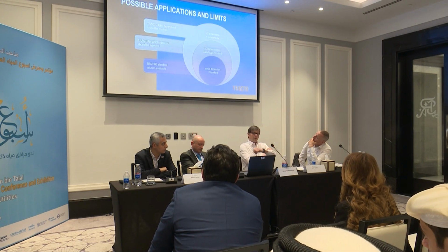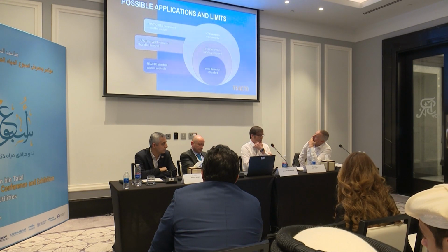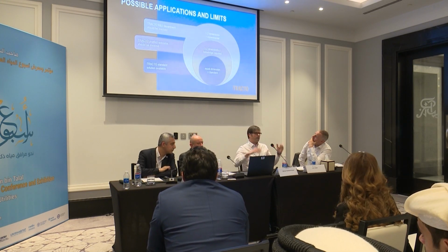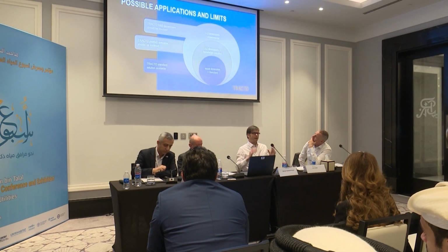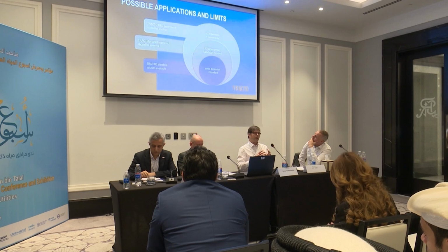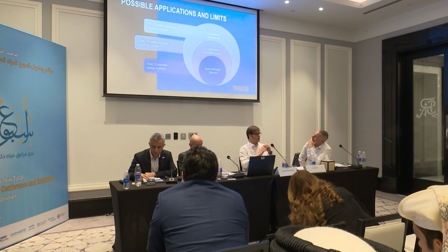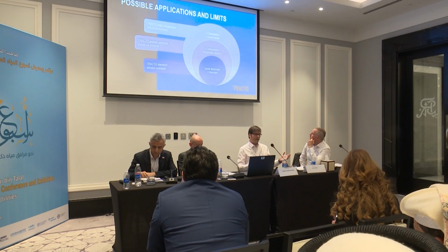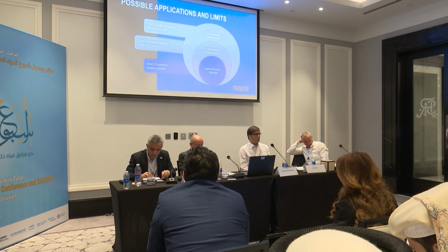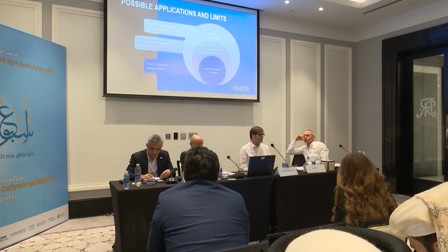So yes, one of our key USPs, unique propositions, is that we can upsize. We can install a larger pipe in an existing host pipe. Most pipe bursts are like for like. So a 300 millimeter ID pipe is replaced by another 300 millimeter ID pipe, but we can double the size. We've even gone more than double.